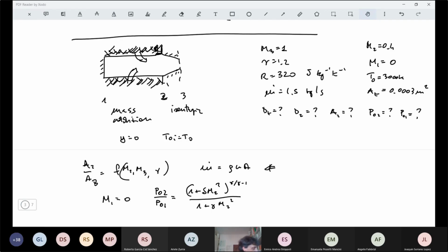At the end, the most interesting result will be the total pressure, and we see that we have isentropic flow here between 2 and 3, so that P02 is equal to P03 will be equal to 75 bar, whereas we have P01 that will be equal to 81.9 bar.